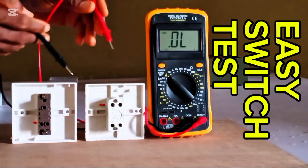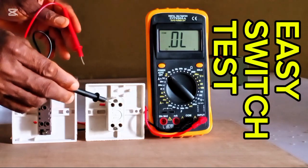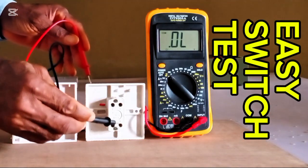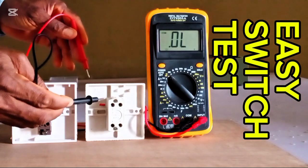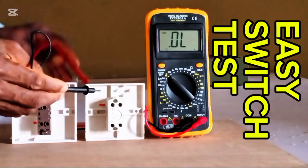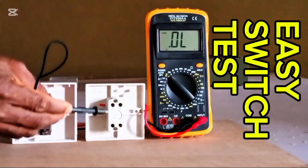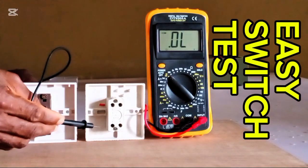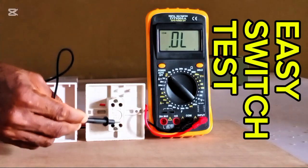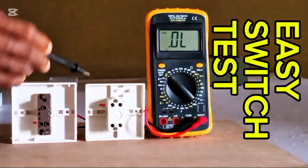All right, so let us go to the intermediate switch. Now, as earlier discussed, the intermediate switch has 4 terminals: line 1, line 2, line 3, line 4. As with the two-way switch, in this rectangular block, there are connecting bars linking 1 to 3 horizontally, 2 to 4 horizontally. Also vertically, 1 to 2, 3 to 4, diagonally, 1 to 4, 3 to 2. This is how they are.